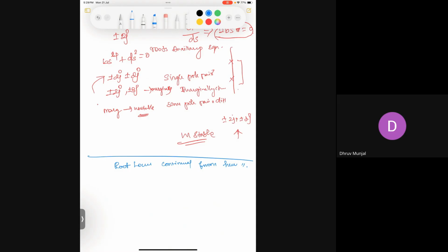Okay, right. The next thing I want to tell is, if someone asks what is root locus in one sentence, how can you tell that? It's the path taken by the roots of the characteristic equation when k varies from 0 to infinity. This is a general explanation of the root locus method. Root locus of any system will tell you how the system propagates when you change your k value from 0 to infinity. That's it. Very simple, right? Based on that propagation, we will try to interpret whether it is stable or not. That is the second product of that method. The method itself doesn't tell whether it is stable or not.